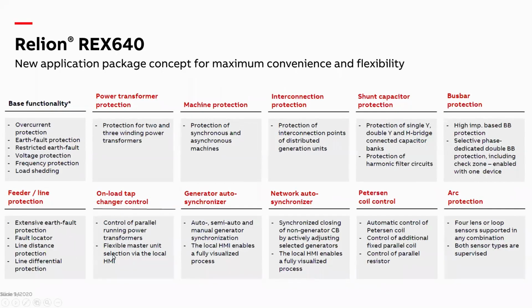And there's a tap change controller, generator synchronization, and network breaker synchronization. Peterson coil control is a very unique feature we have for controlling the Peterson coil for high impedance networks, mostly utility applications. And also we have a package for arc protection.